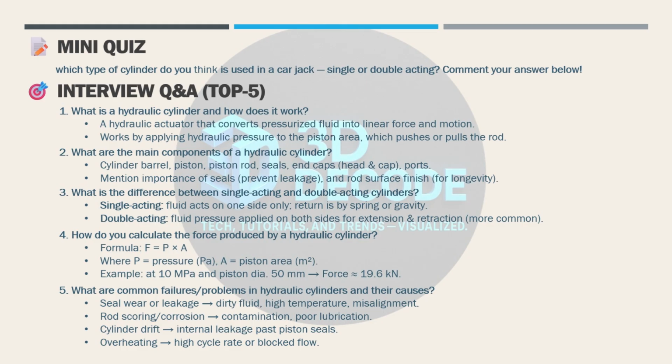5. What are common failures and problems in hydraulic cylinders and their causes? Seal wear or leakage, wear or dirty fluid, high temperature, misalignment. Rod scoring, corrosion, contamination, poor lubrication. Cylinder drift: internal leakage past piston seals. Overheat: high cycle rate or blocked flow.